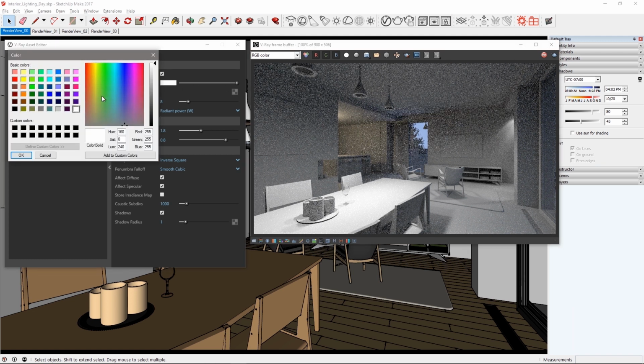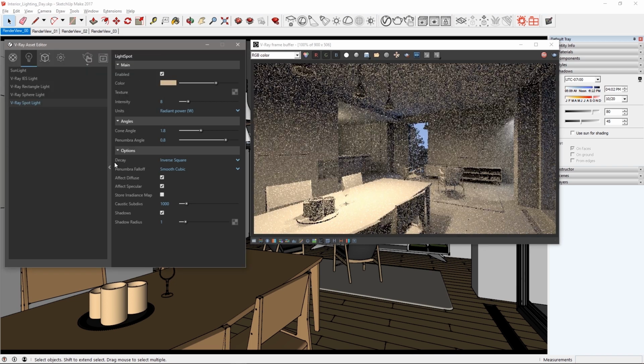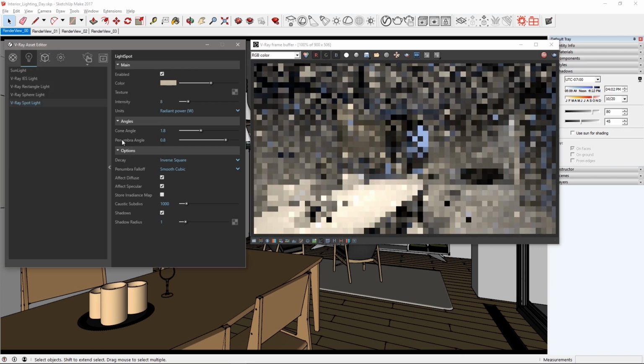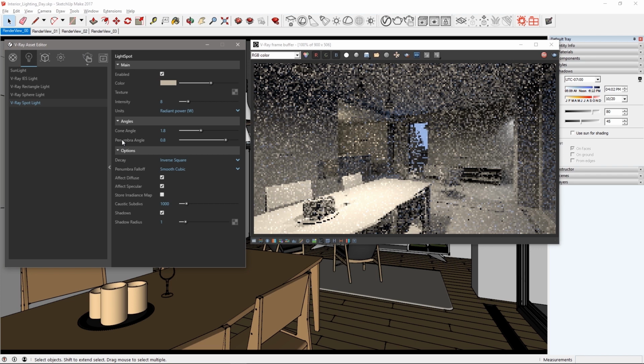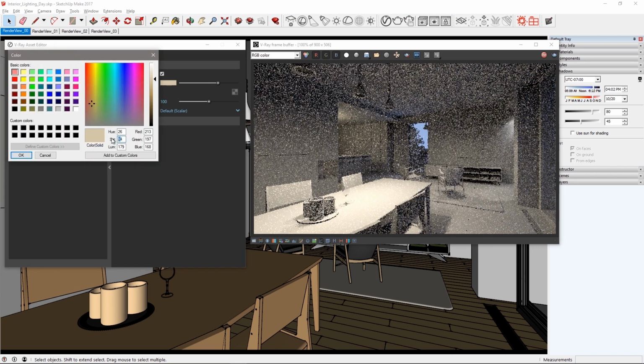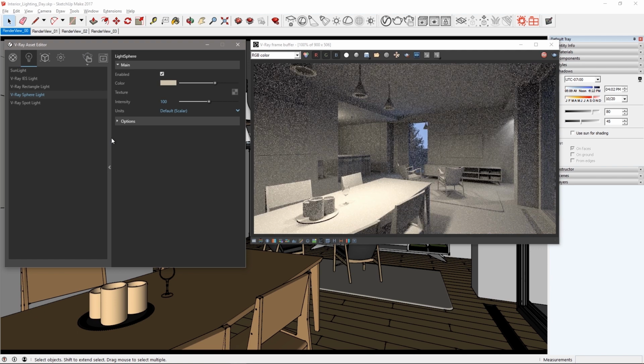Set an amber tone to the spotlight in its color parameter, and you'll see that a little color goes a long way. So I'm going to back off my saturation quite a bit for a nice incandescent look to these lights. I'll do the same to reduce the saturation of my kitchen sphere light as well. Now, since this is a general light in a corner that we don't see directly, using an unmotivated light without a fixture like this can make sense.